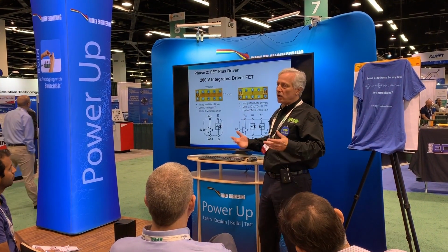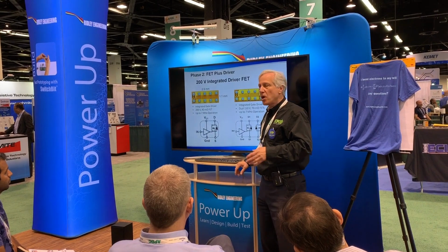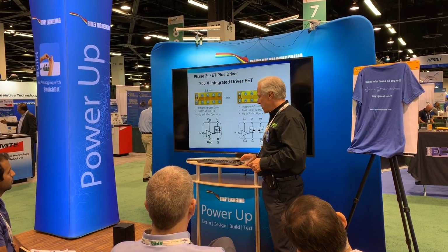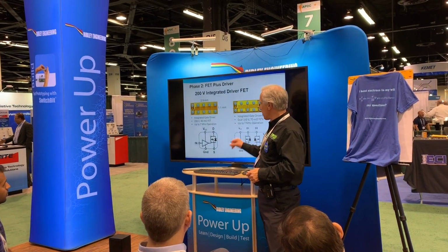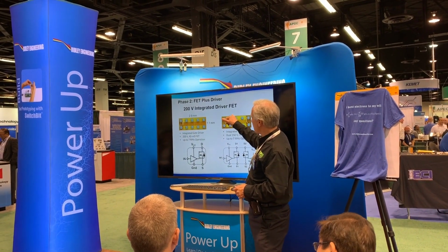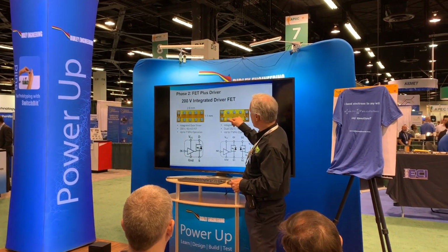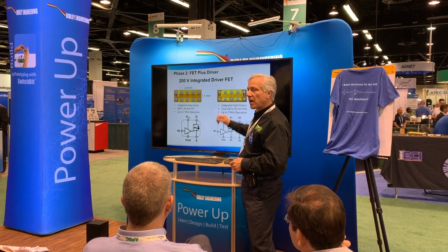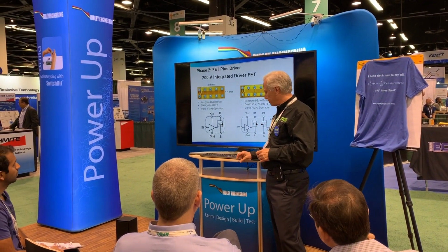These were made for wireless power for Class E amplifiers. We're at 7 megahertz, and it saves a ton of money, because look at how little that area is compared to the device it's driving right here. There's 2 of them. It's just a tiny little area, like less than a square millimeter.